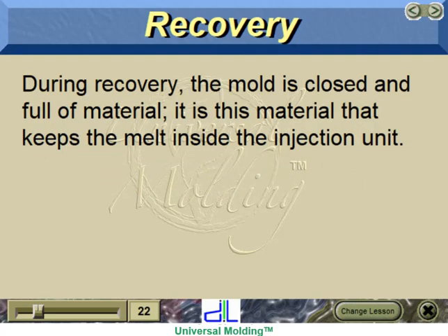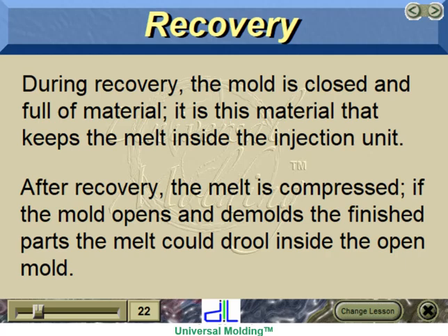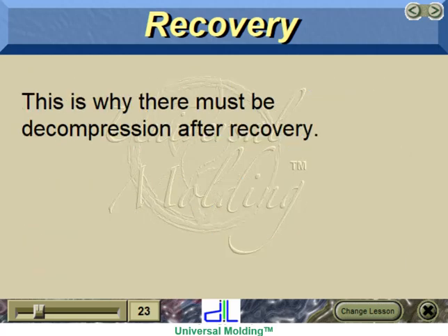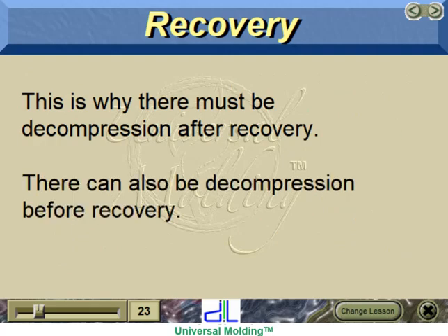During recovery, the mold is closed and full of material. It is this material that keeps the melt inside the injection unit. After recovery, the melt is compressed. If the mold opens and demolds the finished parts, the melt could drool inside the open mold. This is why there must be decompression after recovery. There can also be decompression before recovery.